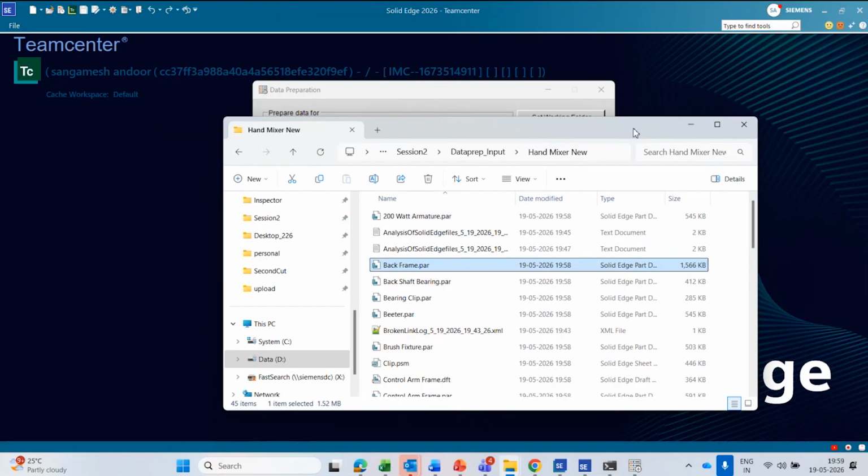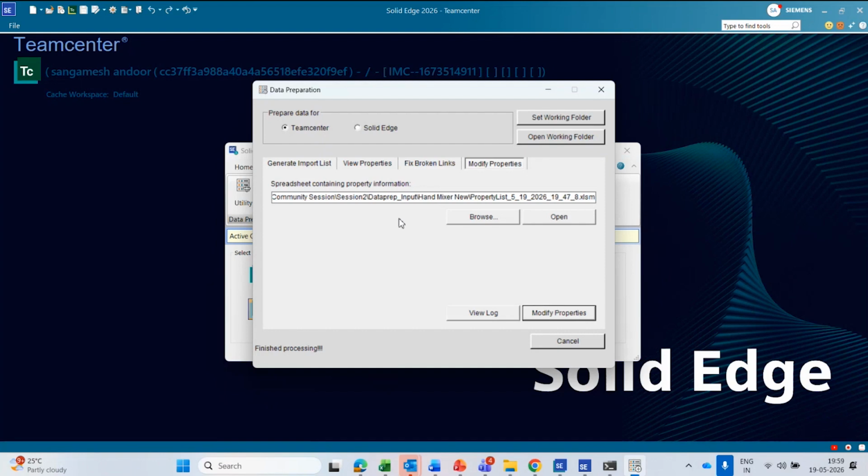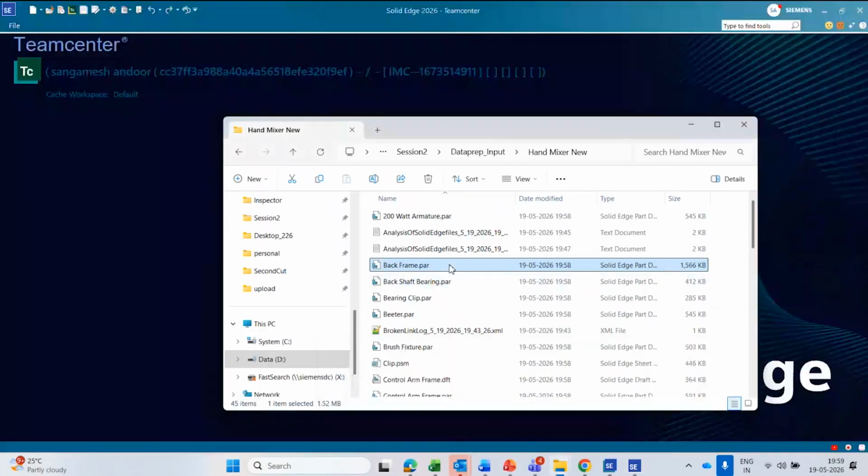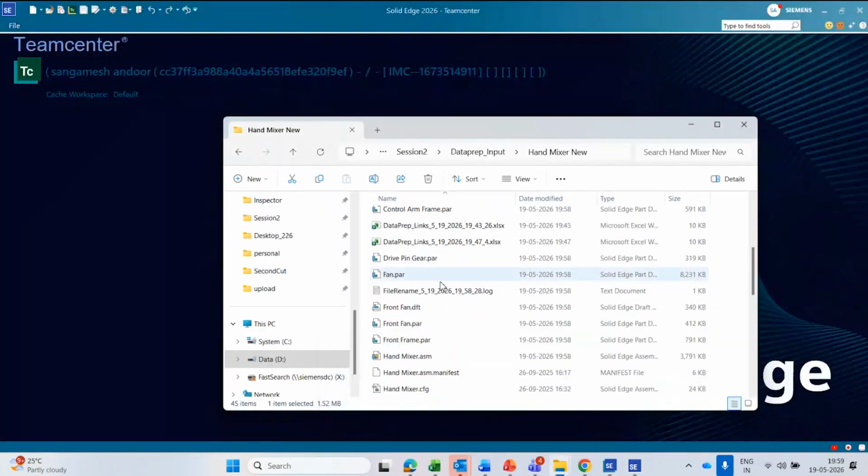Okay. And in case you want to rename the files also, like say in this case you want to rename these files to match the data set or the item revision name, you can use the master list. In the master list itself, you have the option to create a new file name for each of the documents. But I would recommend using the design manager if that is really needed, and in case you want to modify all the component names here.